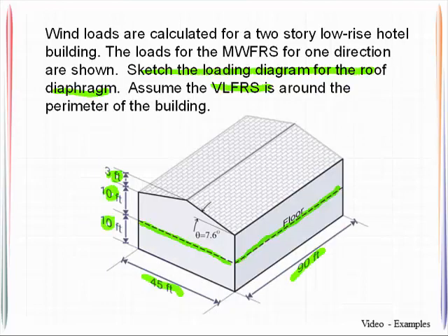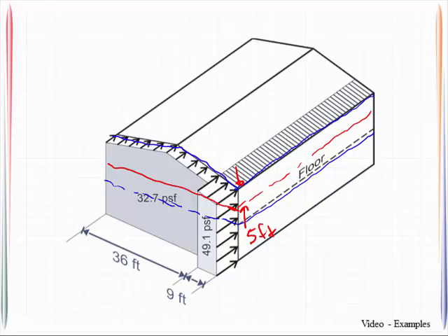You'll recall that 10 feet was the height between the roof and the floor. Okay, so we've got 5 feet there, and then you will recall that we rise another 3 feet to get to the ridge. And so really, if you want to think of it this way, our tributary area to our roof is this, where that's the 5 feet there, and it will rise up to 8 feet.